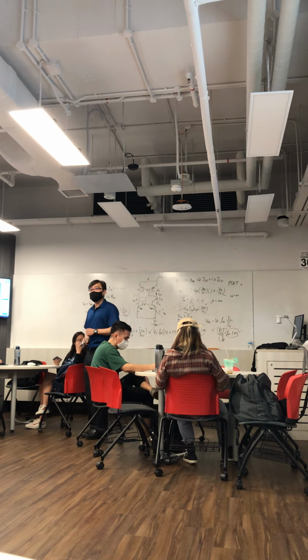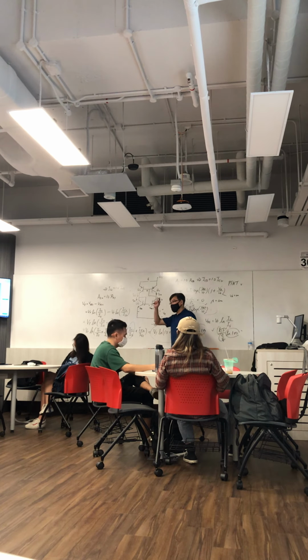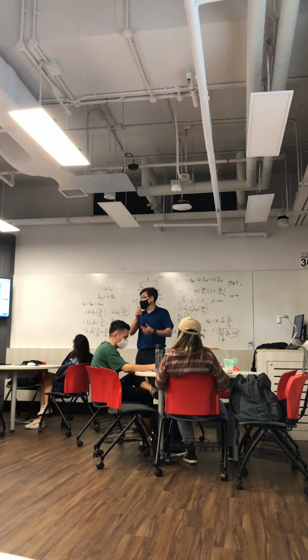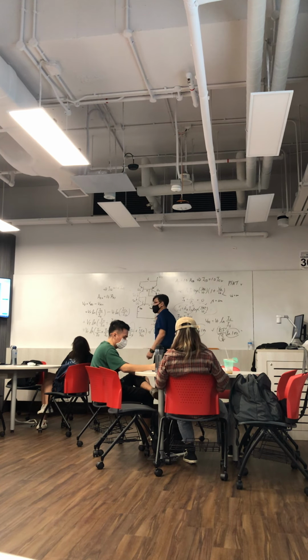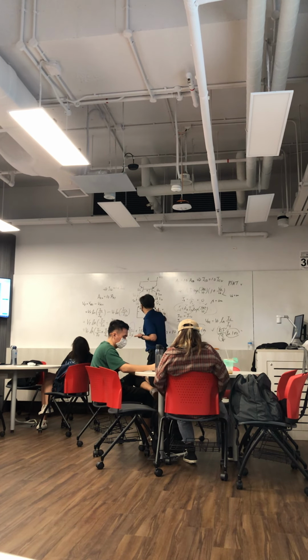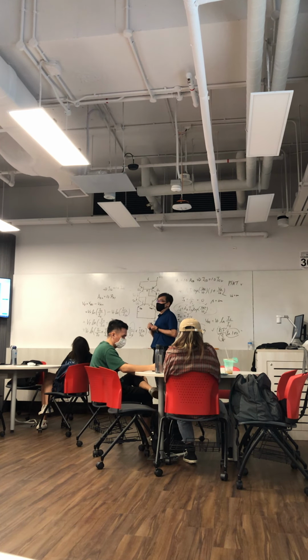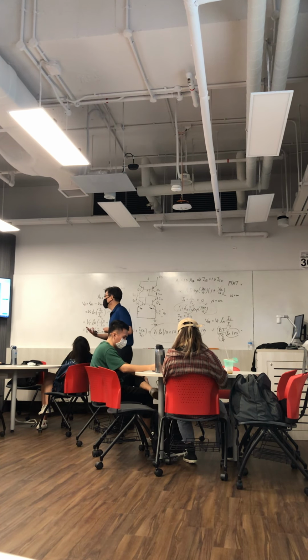So what is good about linearly proportional? It means that if this increases by a certain amount, that increases by a corresponding fraction. So in this case, as long as I can test what the voltage is at 0 degrees, then by looking at the voltage, I know what the temperature is, because it's proportional to temperature.